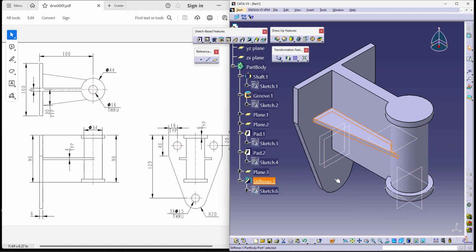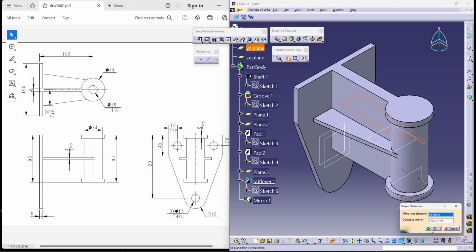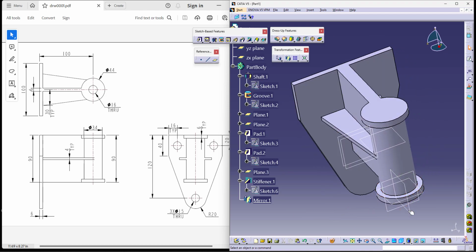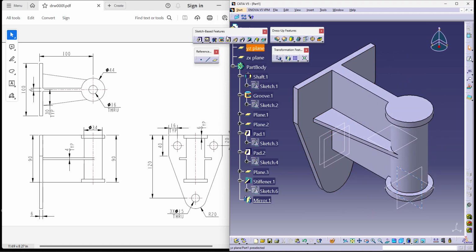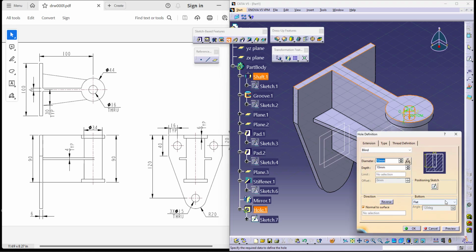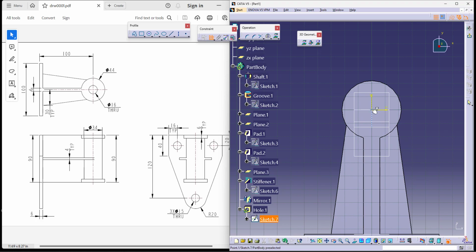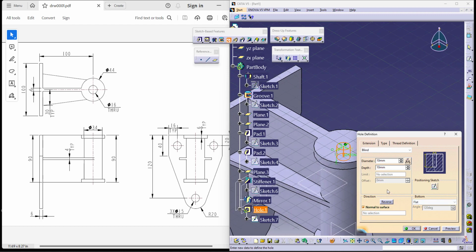We can mirror the same feature onto the opposite side. Again, use a mirror with respect to the center plane. It also creates a feature onto the opposite side. Now you can drill holes. We already know how to do that. The same feature selected. Again, position the sketch. Let's not forget to always maintain concentricity between this, so we don't change the position when the feature changes. It's up to next, and we know the dimension of it is supposed to be 16.